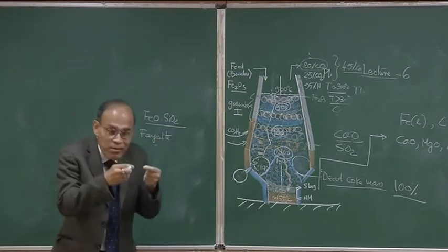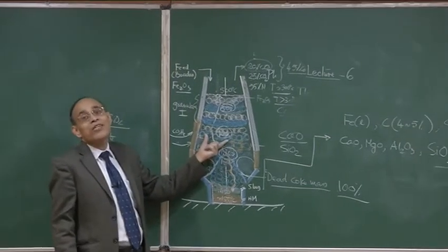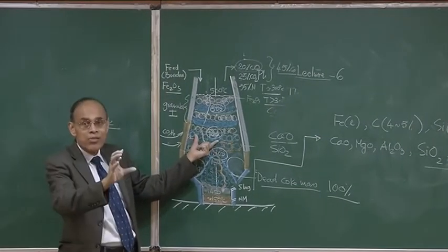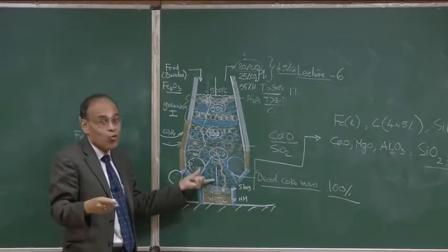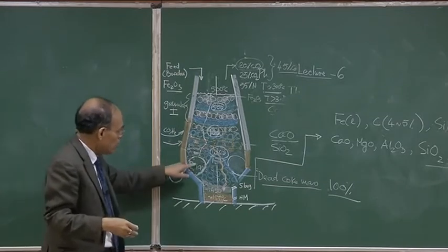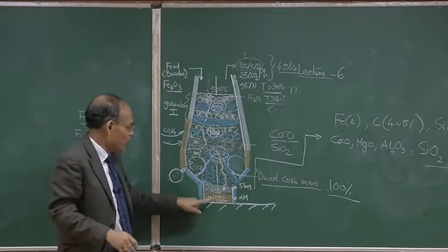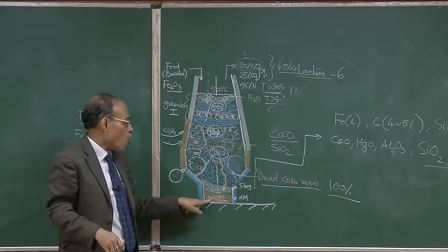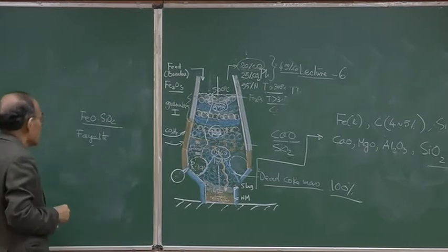And this liquid tries to bond the solid particles, and that is what we see in a cohesive zone, where we can have some lumps. Coke is of course going to be lumpy always, because coke does not melt. Coke remains, either when it oxidizes in the raceway, but elsewhere in the furnace coke is either available as dissolved carbon in the metal, or as lumpy coke within the blast furnace itself.